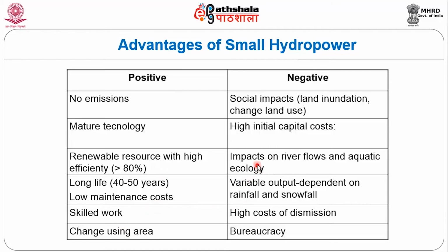There are some negative aspects, that is social impacts will be there, high initial capital cost is necessary, impacts on river flows and aquatic ecology, and variable output dependent on rainfall and snowfall. If there is no rainfall, then we can't have storage, and then we cannot generate electricity. And if it is snowfall, if the reservoir is frozen, then we cannot operate it. And high cost of decommissioning and bureaucracy. So, these are all negative aspects.